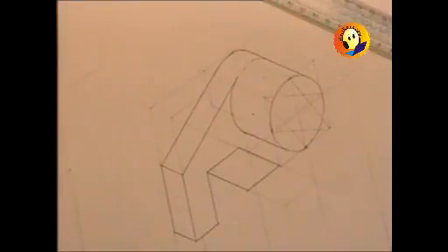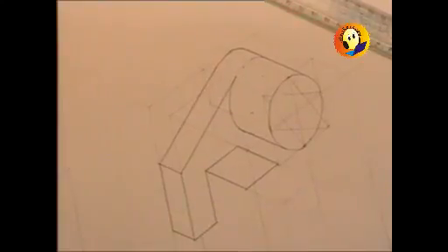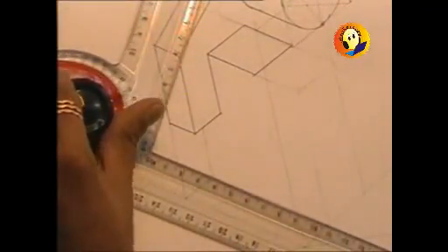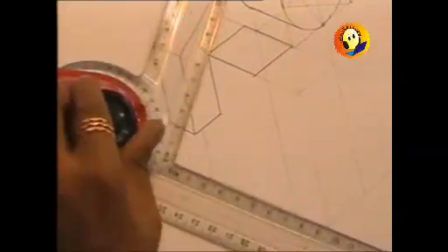Now, the same construction will also be required as we proceed with this plate. And we are given that circular portion which belongs to this particular block here is having a radius of 28, and so we are required to construct a rhombus of side 28 into 2, that is 56.